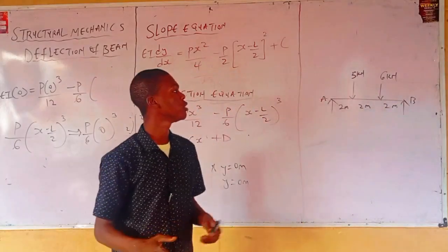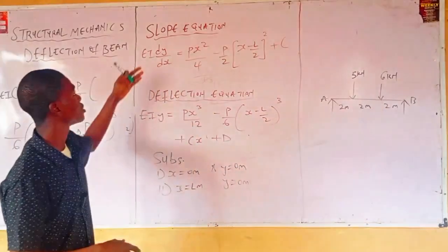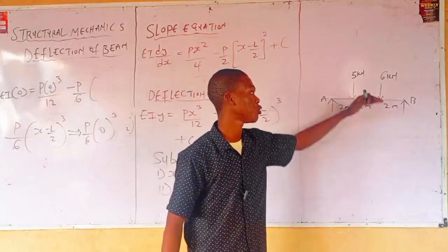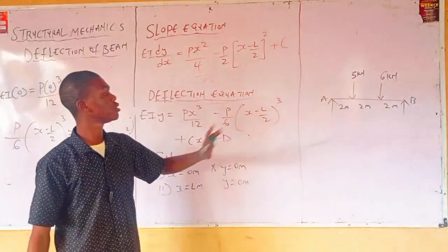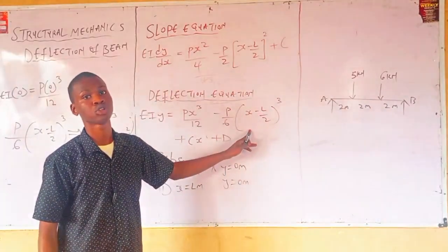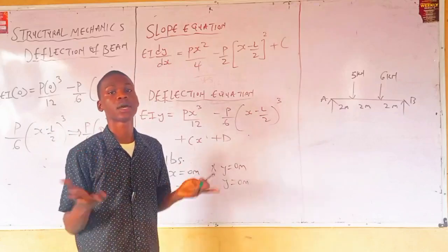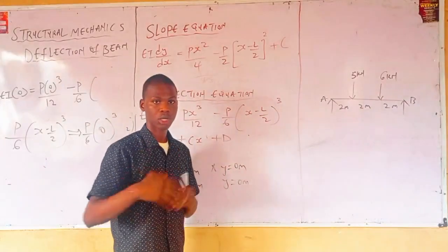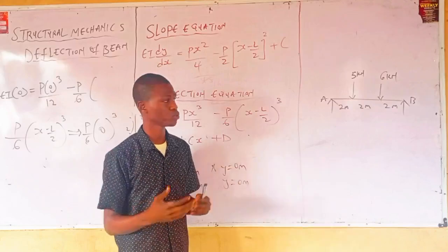The same way from step 1 up to this step that we got the slope and deflection equation, that's the same idea that I am going to use to solve this. But when substituting your boundary condition, this won't be the idea that I am going to use. Any value of your x, let's say your value of x is 10 meter, then you have your 10 meter divided by L over 2. In the subsequent video, I'm going to take more examples to see what we are saying.